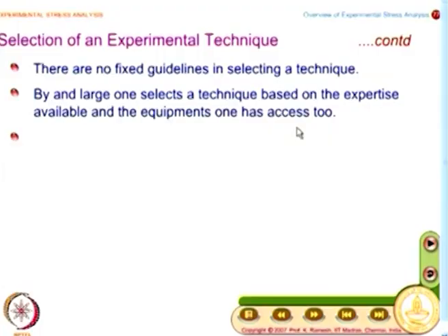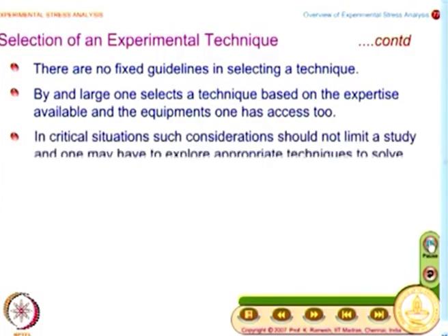If you have not followed the steps, for example, in the case of speckles, if you do not have a good characteristic of speckles, whatever measurement you do later will be erroneous; it depends on the quality. Similarly, if you have not tested the strain gauge, then whatever you measure is what you want. It is not what the system says, that this is the strain value I am experiencing. So you need to have expertise to do an experiment. Keep that in mind. When you become managers, you train your people to acquire this expertise.